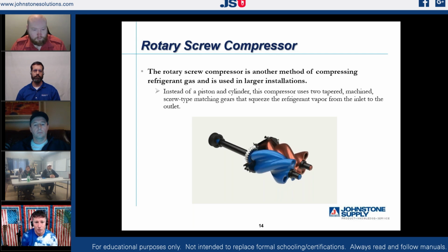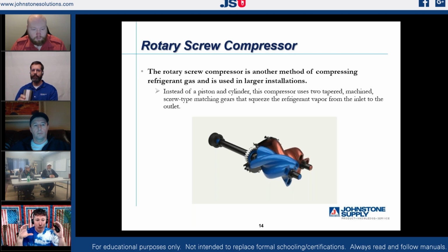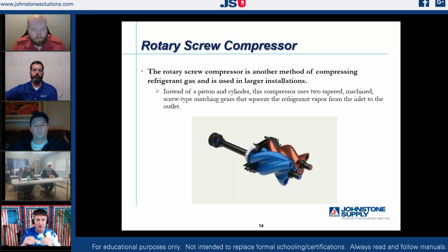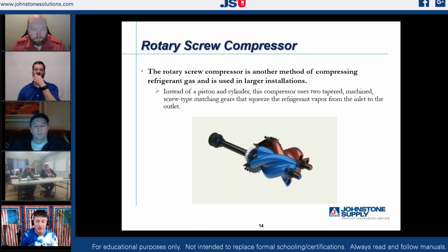If we look at rotary screw compressors, I'm sure you guys have heard the term of screw chillers or screw compressors before. May not have worked on them. I've worked on quite a few of these things. The rotary screw compressor is a different method of compressing refrigerant gas. So it's still just a pump, isn't it? It's bringing in a volume of vapor and it's squeezing it down so that by the time it gets to the end, it's been compressed. And that's all that we do. Anybody ever paid any attention to what a supercharger on a vehicle looks like?